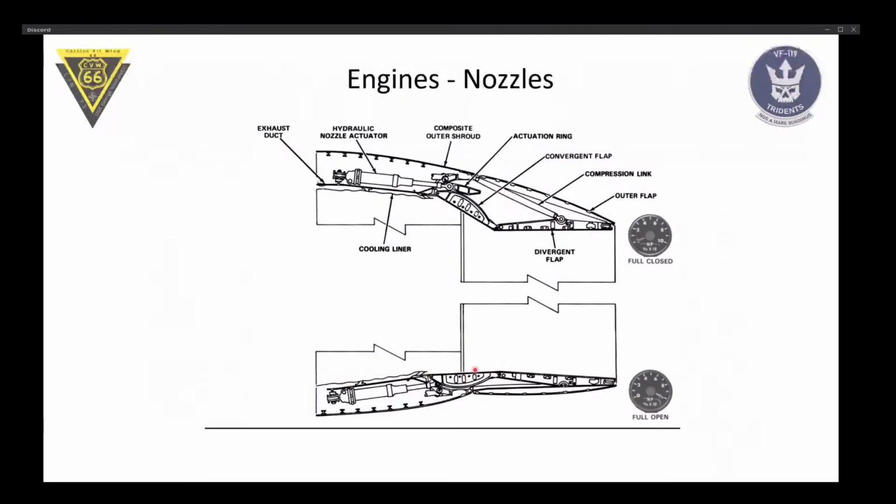And this configuration will depend on our pressure in the afterburning chamber, on our ambient pressure, on our velocity, and on a lot of things. And to find the optimum configuration for the full flight envelope, we have this variable exit nozzle system, which again maximizes the thrust and is another means to increase thrust without actually changing something within the engine. So this is the engine part.